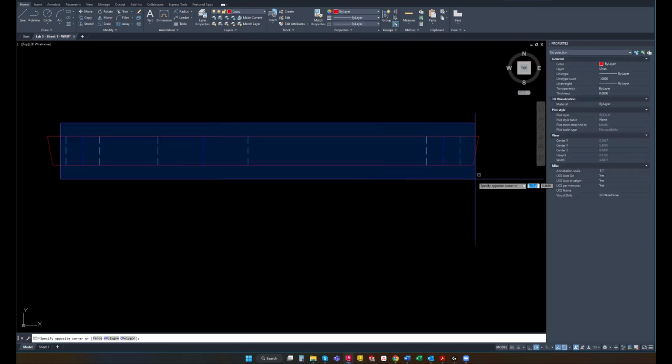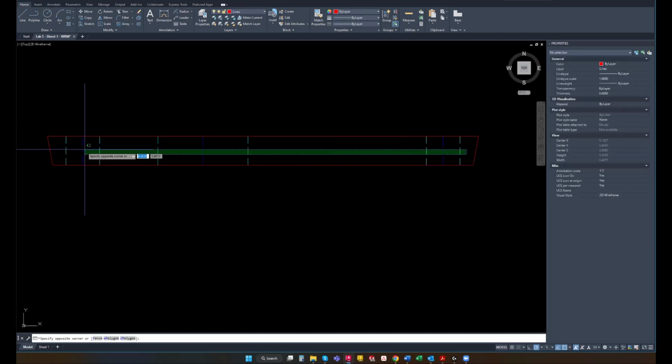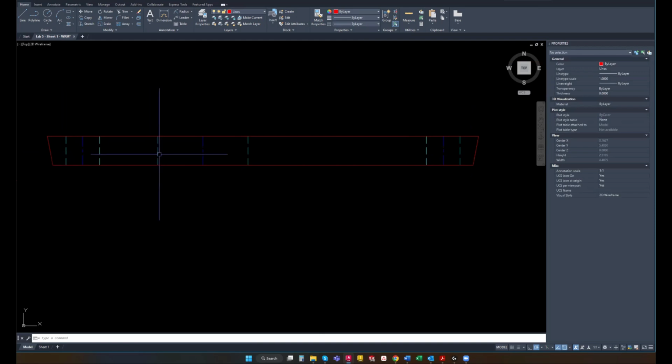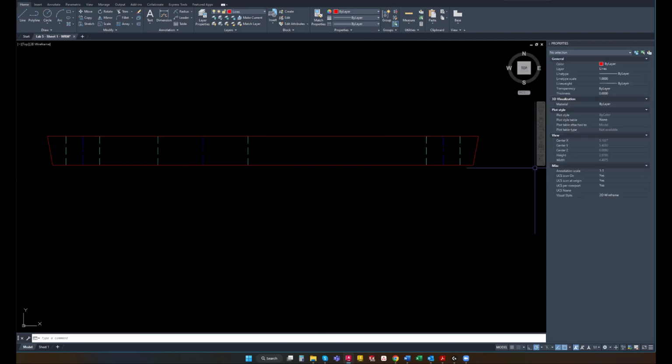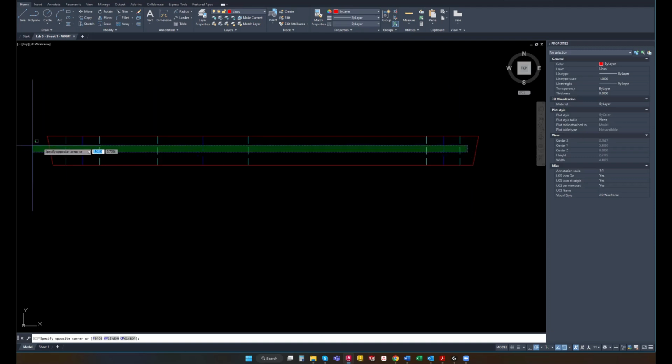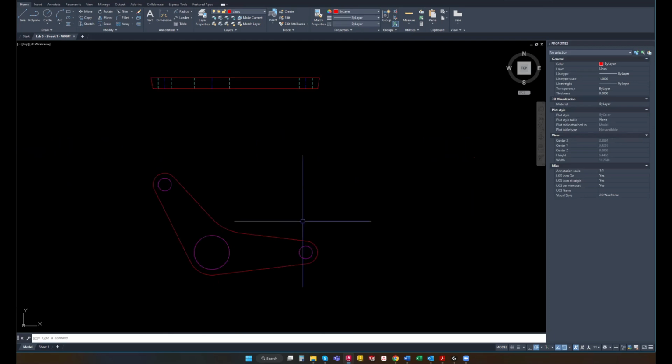Also, I had you change your construction lines to the line type that we wanted. That was a little bit unnecessary. I thought it might have been easier to keep better track of what we're looking at with those construction lines. But technically, because we have set these layers up with those line types, if you just saw over my properties menu, I just changed all these line types back to by layer. And they stayed the same line type. So just keep that in mind there.